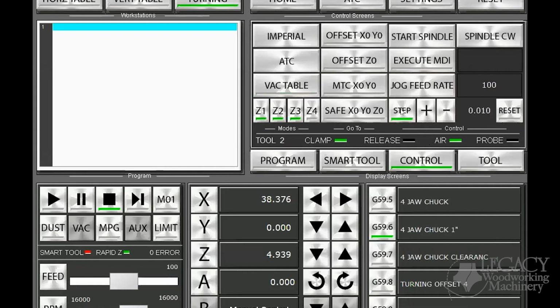Now, when you're rotating and you step jog, this is in degrees. And so this is 1/10 of a degree. It's barely going to move, if anything at all. When I rotate it using the A-axis right here, it's barely moving. So I could increase this to 1/10 of a degree and rotate it, or even 1 degree.